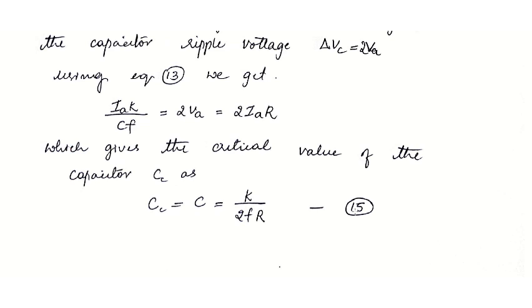So these are the mathematical expressions which can be used to analyze and design the boost regulator. To design the boost regulator, what should be the value for the inductor and the capacitor, we have derived here with the critical value of the inductor and capacitor.